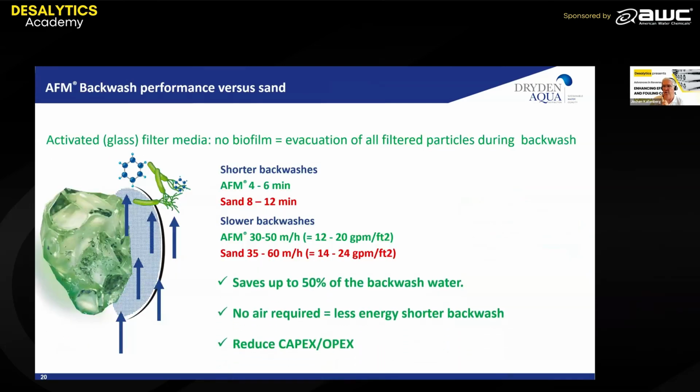If you then go to the backwash, that's a key in media filtration. We have also a lot of savings here because our media is lighter than sand. So in the retrofit, the backwash performance is better because in the same system with the same backwash pump, our media is expanding better. Because we have less biofouling, we also reach a better performance in the removal of the impurities you have filtered before. This goes down up to savings of 50% of backwash water and also savings of a lot of energy.